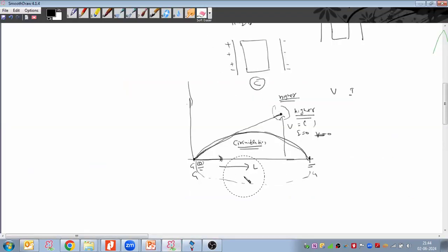Taking the same example, suppose on one side I have done the grounding. Here circulating current will be there, but it is not getting any path. Here the voltage would be zero, and when I am going away from the source, then on the other end of the cable sheath, voltage is inducing.